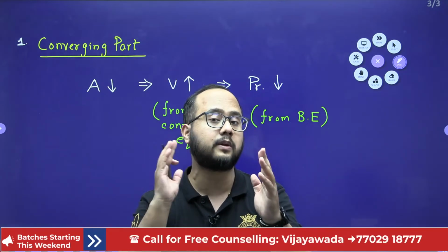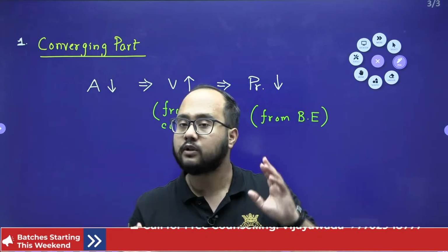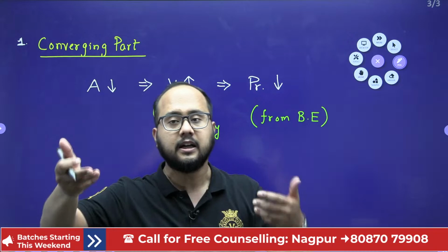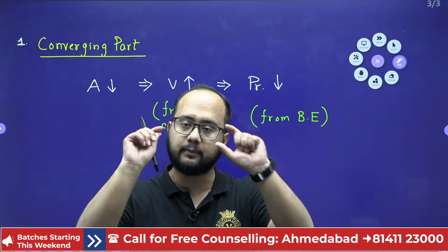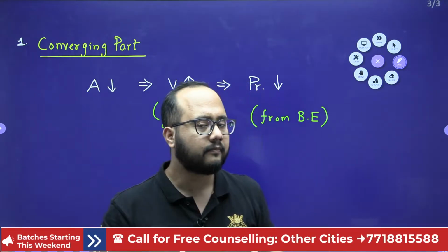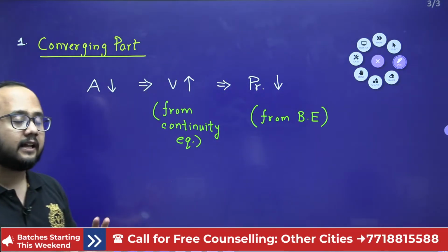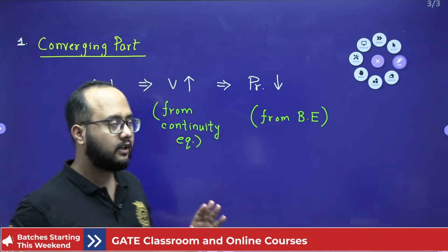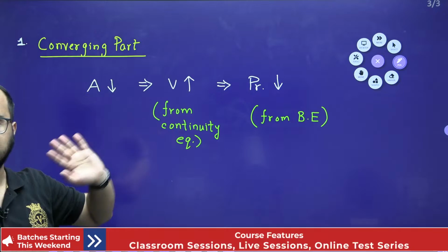The summation of pressure plus kinetic is what? Constant. So as the velocity head or the kinetic head increases, the pressure head is going to decrease, because the addition of both terms is constant. So from that I can easily say, as the velocity increases, the pressure should be what? Decreasing. This is the basic point you can understand here.